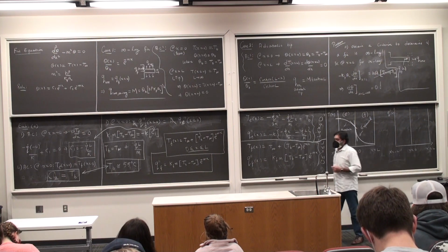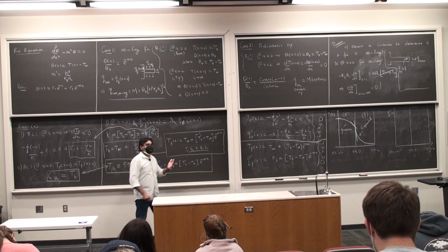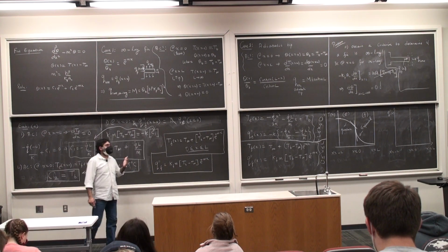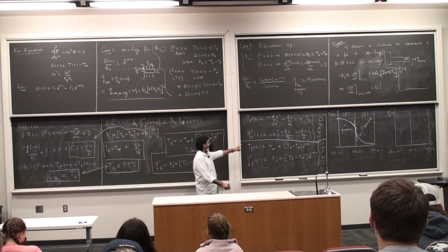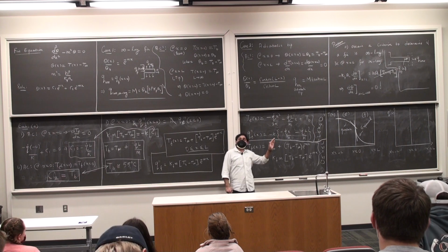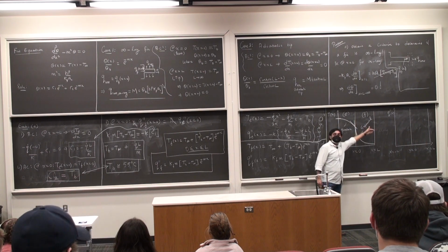And then we have the heat flux profile. At x equal to minus L, the heat flux is 0 because the wall is insulated. And as you can see from the expression here, the heat flux is linear with respect to x, so it is increasing. And I know that the heat flux is positive because the heat direction is along the positive x-axis.